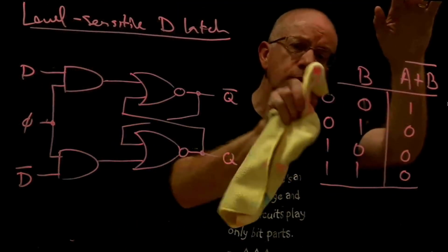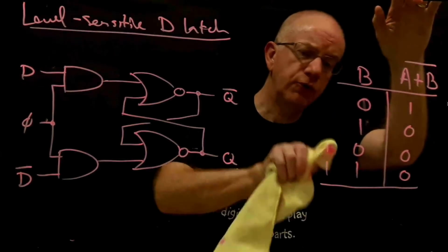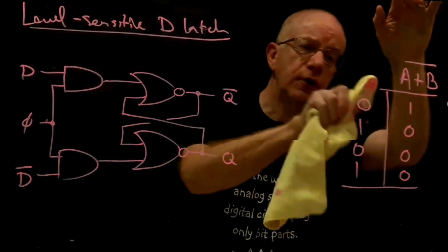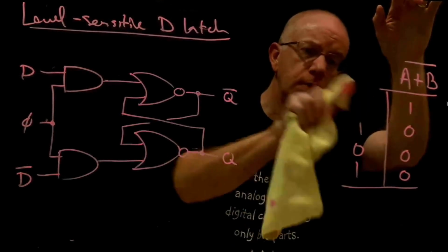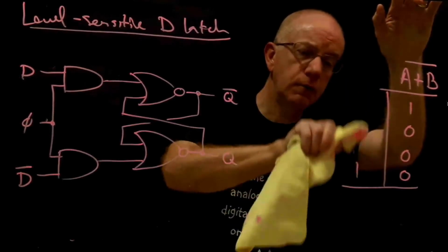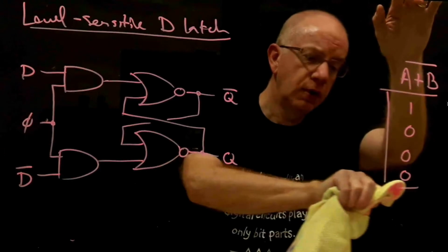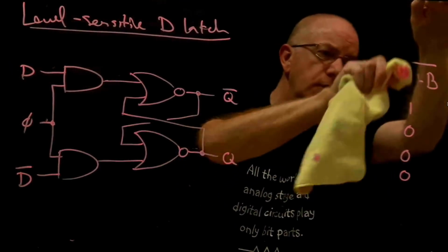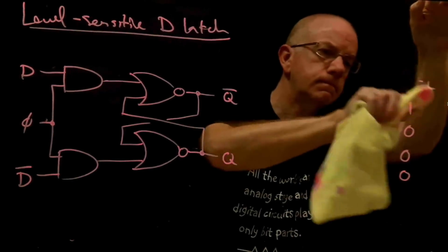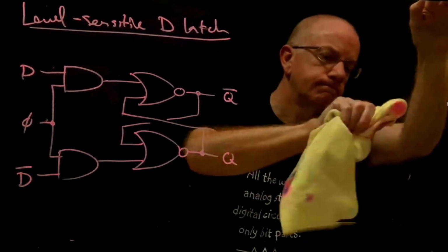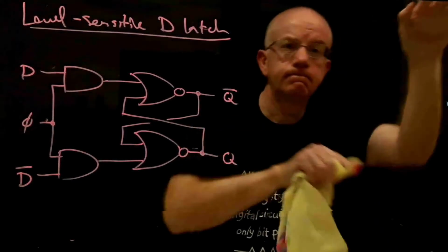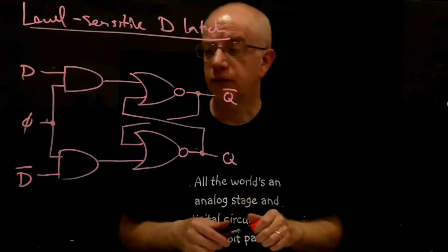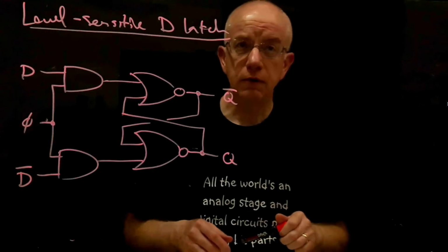But rather than doing that, since this is a course about transistor-level circuit design, we can design a fairly monolithic gate that actually has 3 inputs in order to design our level-sensitive latch. So we're going to do that. Right, we're VLSI designers in this class, not standard cell designers.